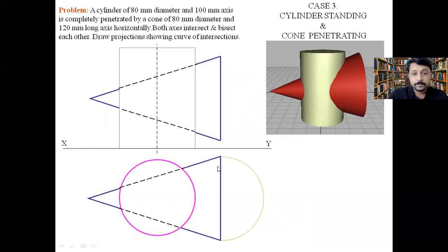Now this is the method of partition, you can say. There is a method where you can go with the standard or traditional method, like drawing the side view and going from there. And this is also one of the advanced methods where you have this particular cone. In that case, you can just take the center point, draw a semicircle and make the parts.